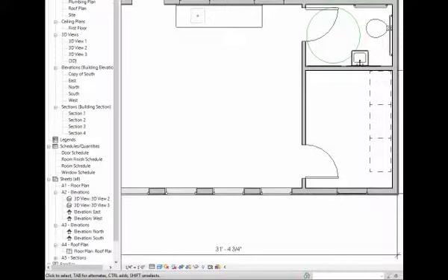We could go ahead and place those individually, and that works just fine. The only disadvantage of placing them individually is if something moves, they don't actually move together. So what I'm going to encourage you to do, I'm just backspacing to delete these, is, when you do have a string of dimensions, choose the Align tool, and instead of placing them individually, place what's called a string of dimensions. I'm going to come here, but as opposed to placing it, continue and choose another thing, and that'll give me a string of dimensions. Now they're considered to be a single string that's all hooked together.